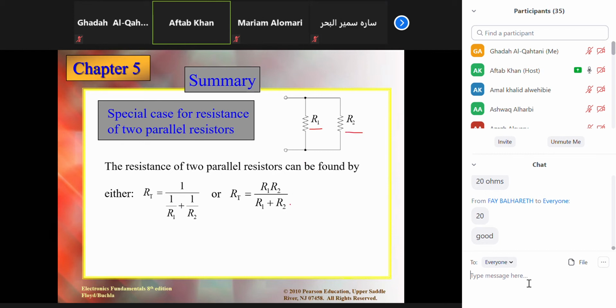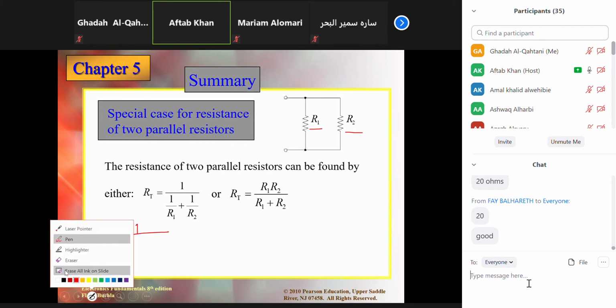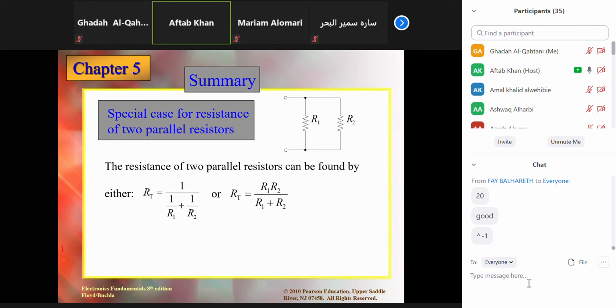So rather than that formula, even though it is the same thing, see, if I just write it for you, RT is equal to, what was that formula? 1 over, or just don't say 1 over, is it just the inverse version? RT is equal to 1 over R1 plus 1 over R2, because they are two only, and this is an inverse, by the way.